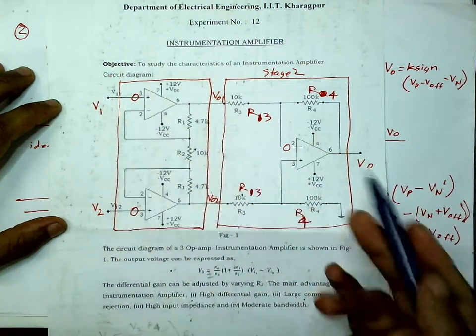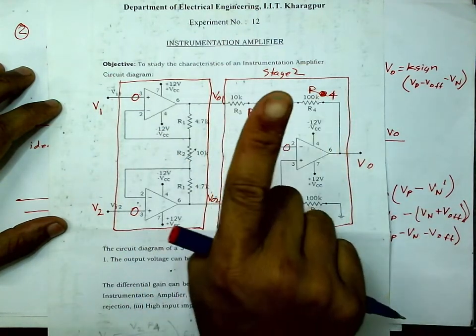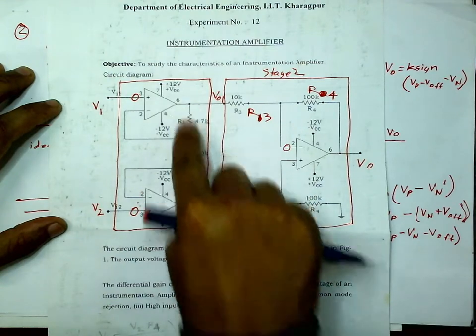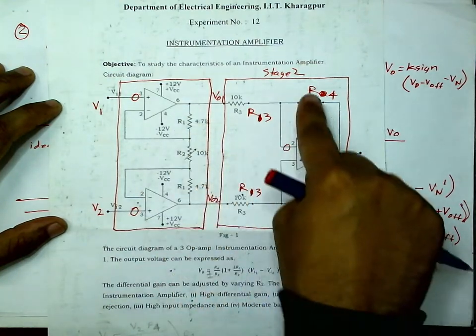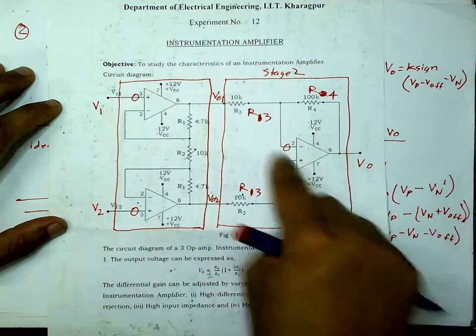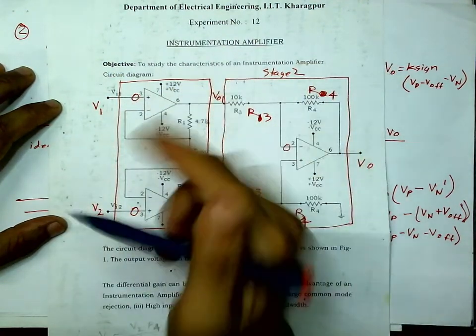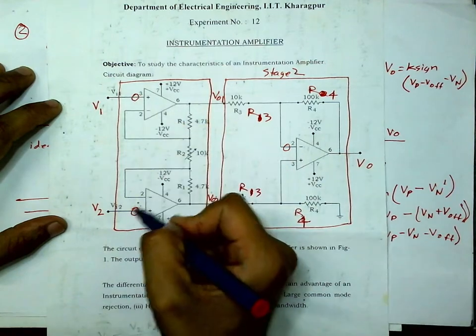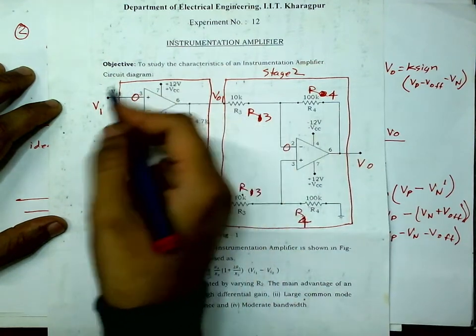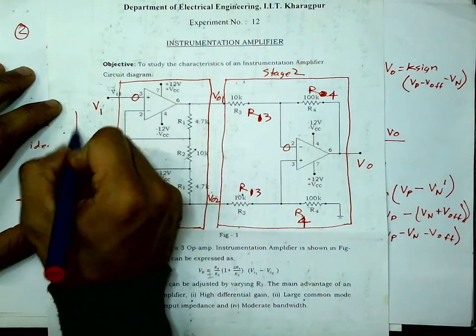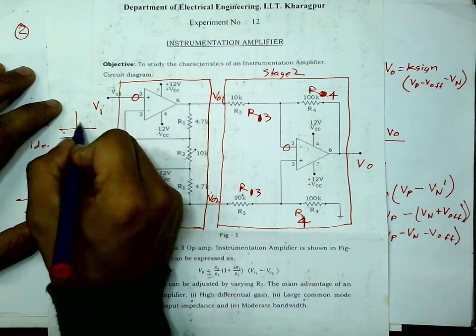So two possible reasons are, number 1, these resistances may not be exactly the same, or reason number 2 is that because of these offset voltages, these op amps might have static characteristics which look like this.